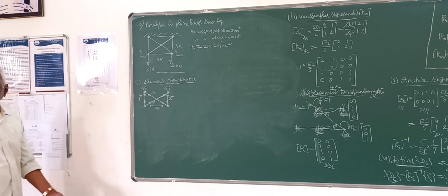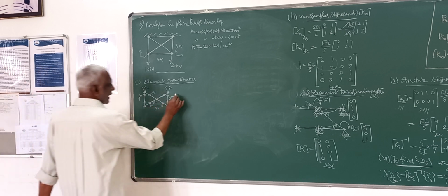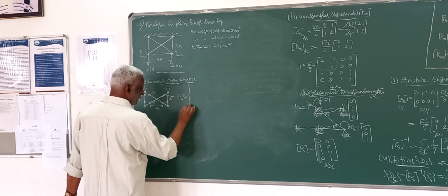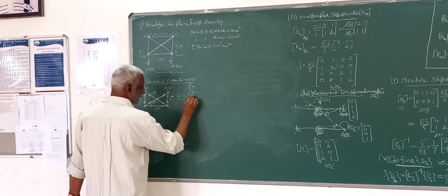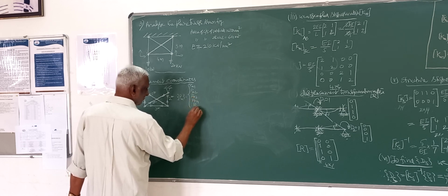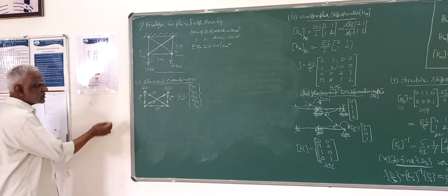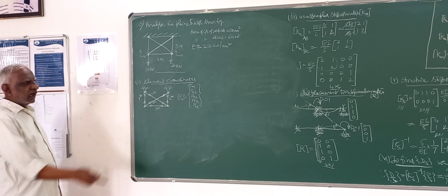So these are the element coordinates. The element coordinates are nothing but the internal member forces which we have to solve during analysis. So that is PM, which we have to determine, PM1, PM2, PM3, PM4, PM5. These 5 internal member forces, whose positive direction is taken by the coordinate with tensile positive, I have indicated.